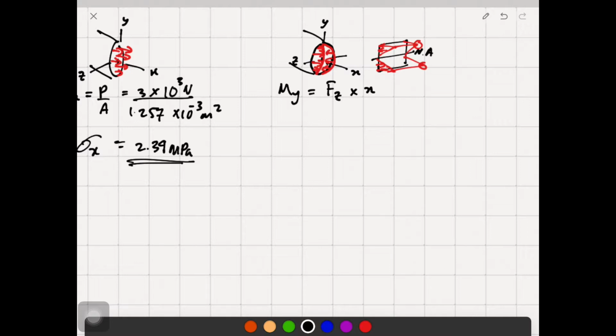I think we did that when we began with the free body diagram. Just want to recap this again clearer here. You can go back to the free body diagram again. We mentioned that this is just 1 kilonewton times the distance. So you get 250 Newton meter. That is the unit for the moment.